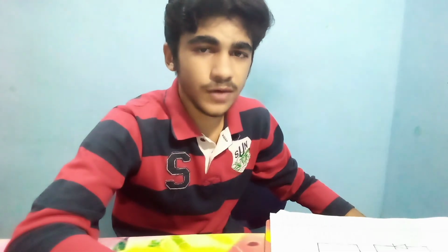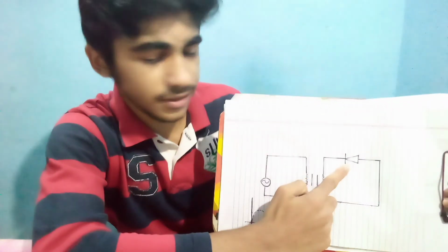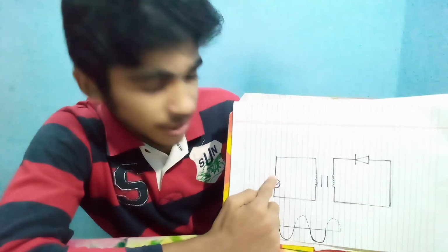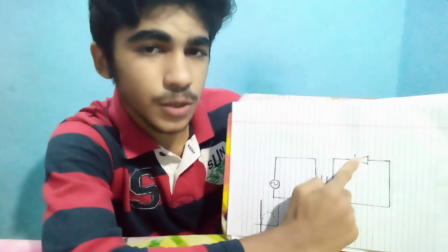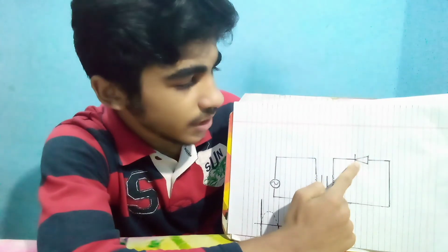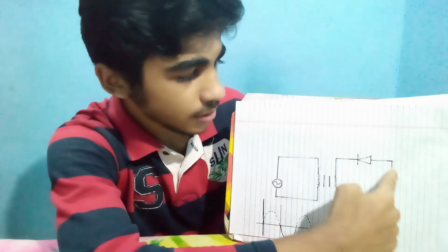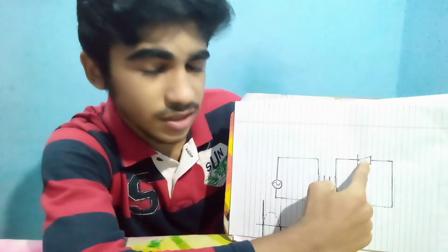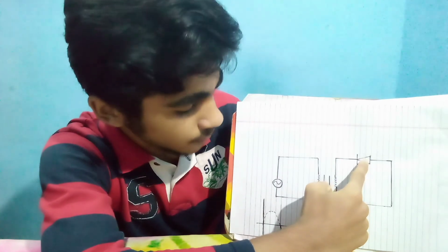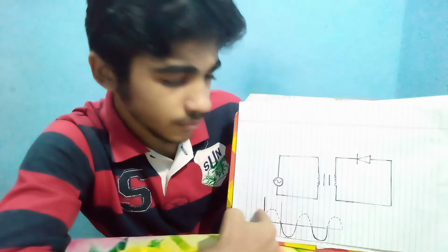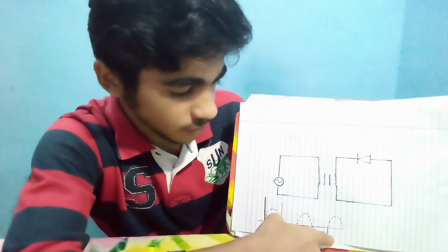And that's what happens in a positive half-wave rectifier. We can also make a negative half-wave rectifier just by turning the diode like this. So it all depends on the diode's configuration. When I apply a voltage, the positive half cycle will not pass through this diode because now the diode is in the reverse bias condition. When the negative half cycle comes, it will pass through the diode because now it is in the forward bias condition. If you look at this graph, you can see that there are no positive waveforms, only negative waveforms.